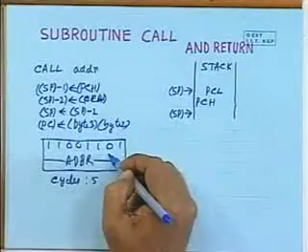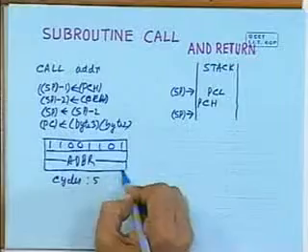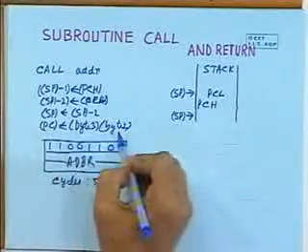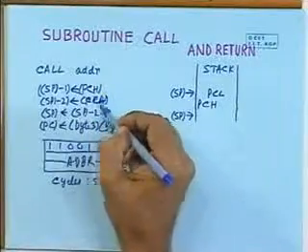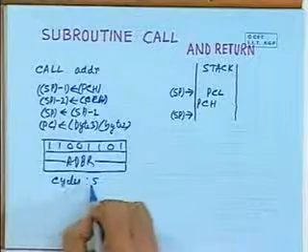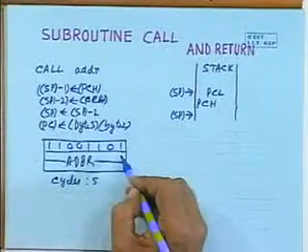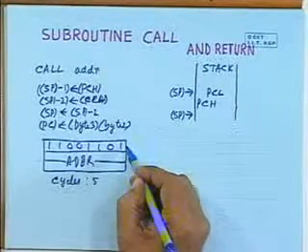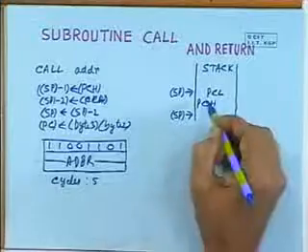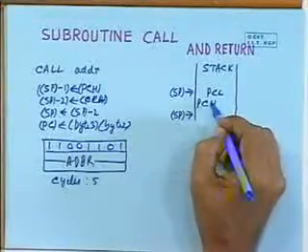You have to not only fetch these 2 bytes, which is provided as part of the instruction, but you have to load them into the program counter, and before that the program counter has to be loaded into the stack. That's why the total number of cycles required is 5. That means it will perform machine code fetch cycle, followed by 2 read cycles, then followed by 2 write cycles into the stack pointer stack.